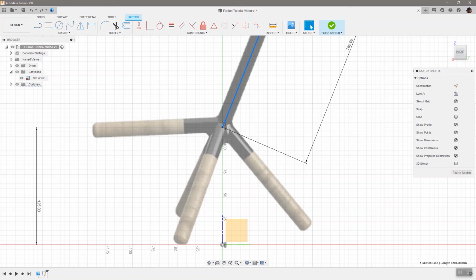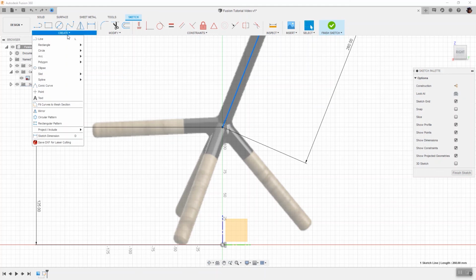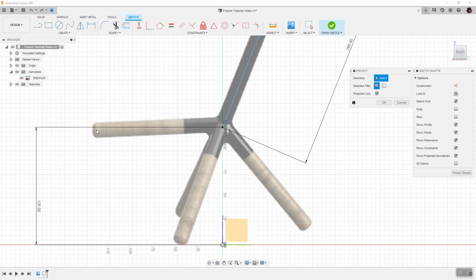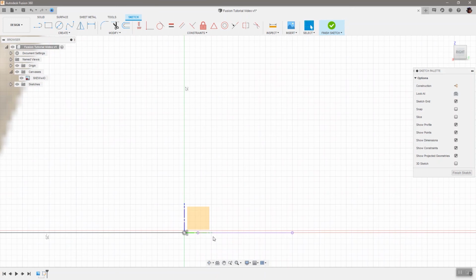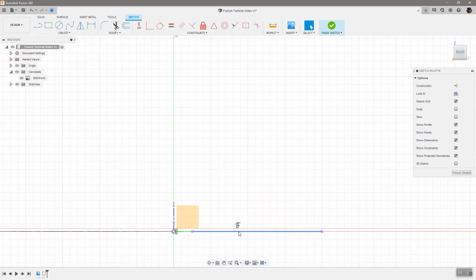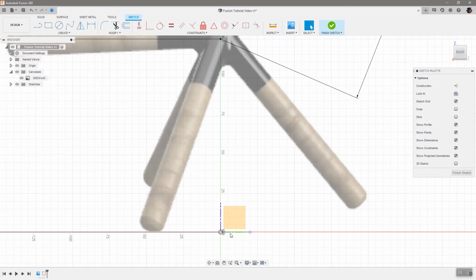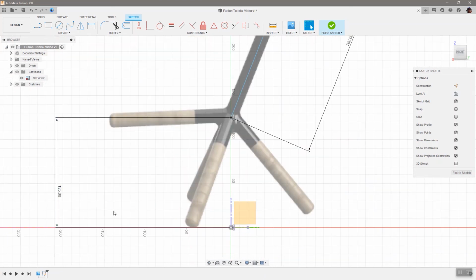And this can be done in this way. Create a projection, and we are going to project something. We have a pop-up window that turns up, very similar to before. It will ask us what external geometry we would like to project, and we can select that axis. We can see it here selected, and then we can say OK. For some reason, we create a very small, very faint purple line. I would prefer this to be larger, quite honestly, but it is the way it is.